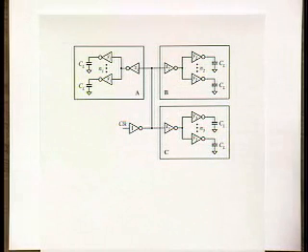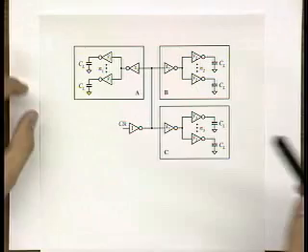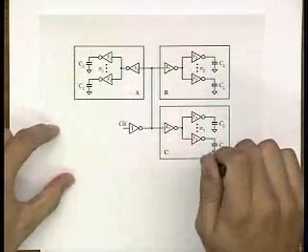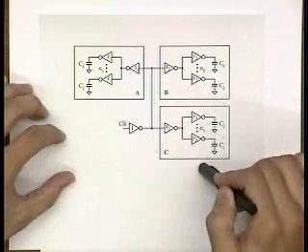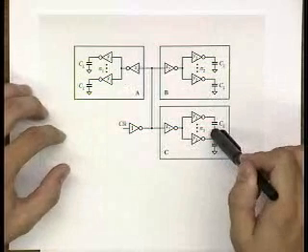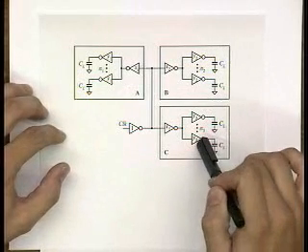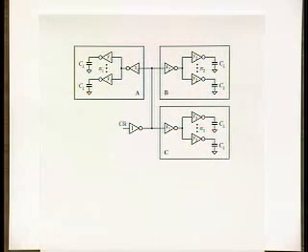Then the next question I'm going to ask you is, let's assume we don't really need to be that precise. We can tolerate a little bit of skew between delays in blocks A, B, and C, and still have good timing. Then if you are given these skew budgets, you first need to determine, based on the size of the blocks, which skew number you're going to assign to which block to make sure that you minimize your energy. So it's giving you a little bit of timing slack, but reducing energy.